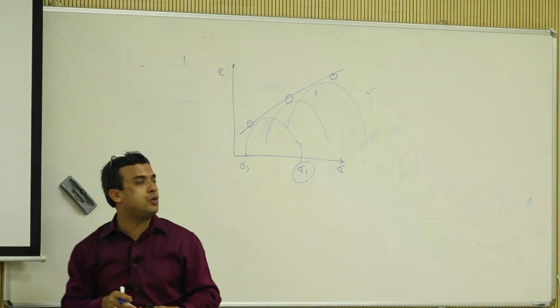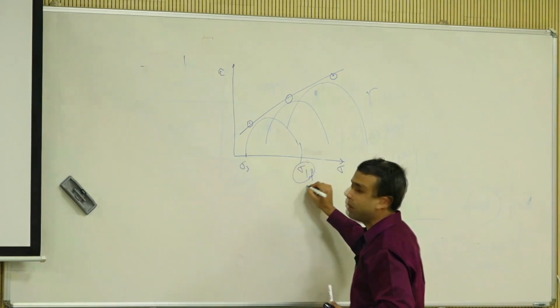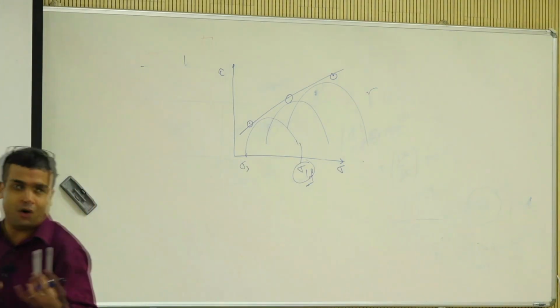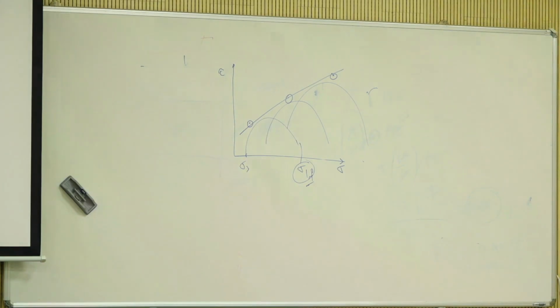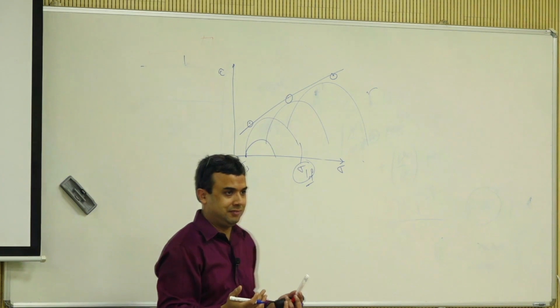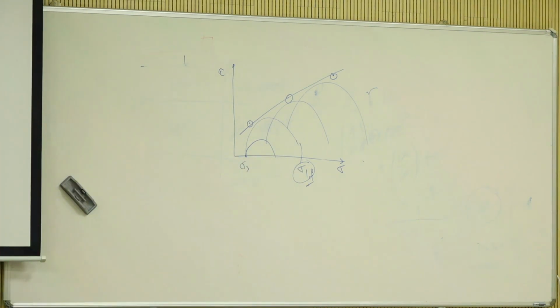I actually try to call it not really sigma 1. Sometimes I call it sigma 1f, because it is touching the failure plane. So I call it sigma 1 at failure, not just any random sigma 1, because this is also a sigma 3 over sigma 1, right? It's not a failure condition. It's not touching you. It's not defining the boundary and stuff.